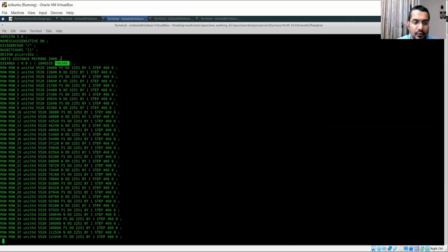And what will be the unit? So this is set by this statement, units distance microns. So this is the database unit per micron, that is 1 micron equals 1000 database units. So these are database units. So if you divide these numbers by 1000, that will give you the dimensions of the chip in micrometer. So that would be one of the assignments you would be getting.